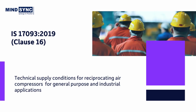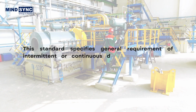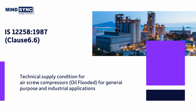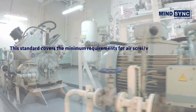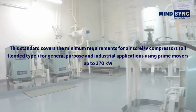The first standard is IS 17093, technical supply conditions for reciprocating air compressors for general purpose and industrial applications. This standard specifies general requirements of intermittent or continuous duty reciprocating air compressors for stationary application. Next, technical supply conditions for air screw compressors, oil flooded, for general purpose and industrial applications. This standard covers the minimum requirements for air screw compressors, oil flooded type, for general purpose and industrial applications using prime movers up to 370 kW.